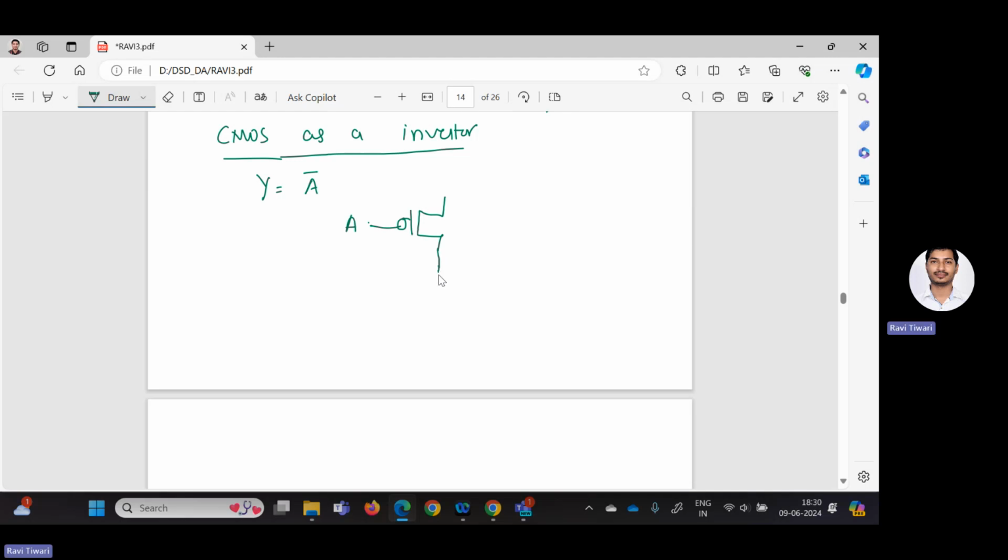At the bottom, we have to draw that by using the NMOS. At the top, you have to provide with a VDD. At the bottom, you have to provide with a ground. Okay, clear, right? Now from the center, you have to take the output. This is V out. And as I told you earlier also, inverter is already there with NMOS and PMOS, so it's an inverter only.